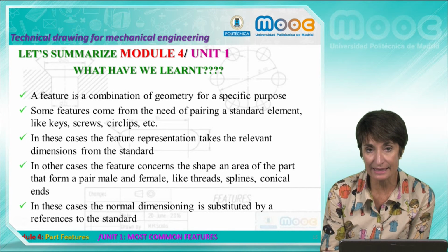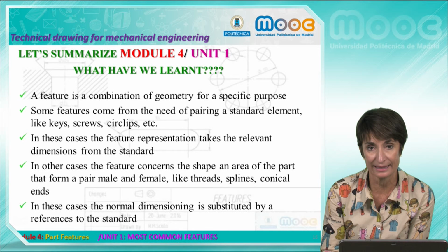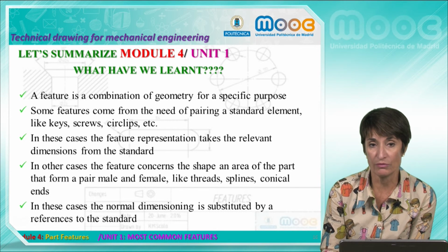In other cases, the feature refers to the shape and area of the part that forms a male and female pair, like threads, splines, conical ends. In these cases, regular dimensioning is substituted by reference to the standard.